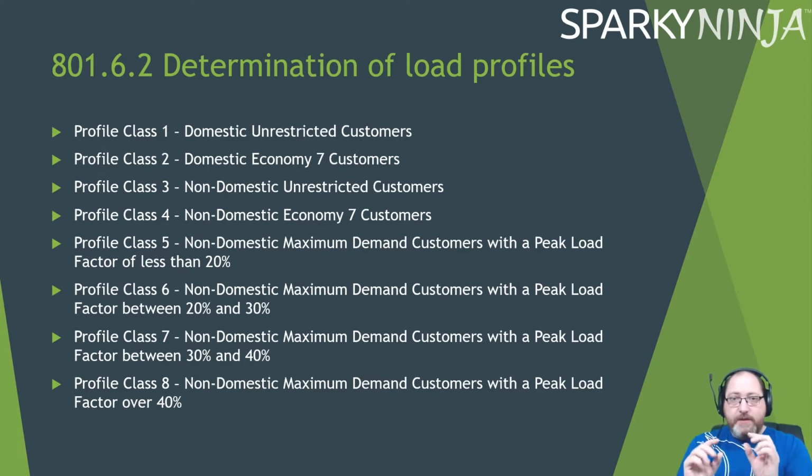One of those circuits may be best for the outer circle or the outer edge circuit, because if you've got daylight coming in, you want to have a recognition that the lights that don't need to be on in the daytime due to borrowed light from the sun are a different profile, and so that can be controlled or just switched off and only turned on at night time. For example, all this is load profiling.